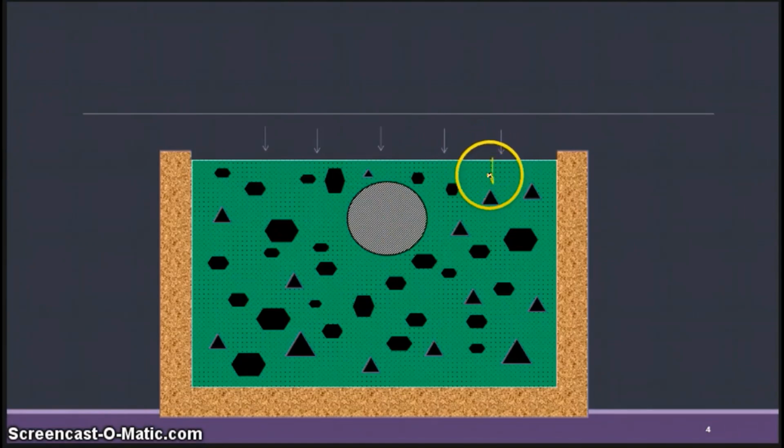When it subsides, it's going to go down like this. Whatever amount of concrete was present here is going down. Here it does not have much resistance, so it can go down easily. Water will have a tendency to come up, and it will be coming up as bleeding water, and it will again be subjected to evaporation. So water will come up and the heavier material goes down.